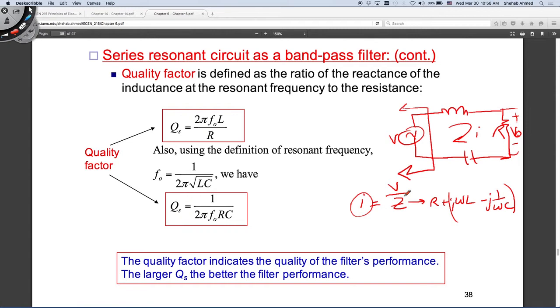So we would like at the non-resonant frequencies to have this effect of the inductance and capacitance, or this impedance, very large. Maximize the effect as much as possible when we are away from the resonant frequency, and then at the resonant frequency have the impedances, this L and C impedances, disappear. Right? That's the objective here.